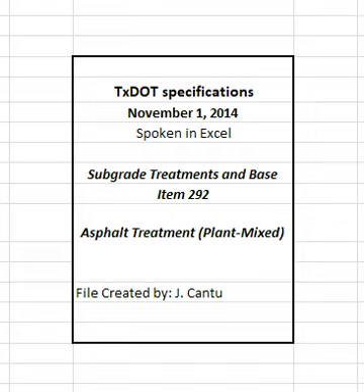4.6.3.1 In-place air voids. The engineer will measure in-place air voids in accordance with TEX 207F and TEX 227F to verify that in-place density requirements of Section 292.4.5.1, density control, are met. 4.6.3.2 Irregularities. Remove and replace, at the expense of the contractor and to the satisfaction of the engineer, any mixture that does not bond to the existing pavement or has other surface irregularities identified by the engineer.